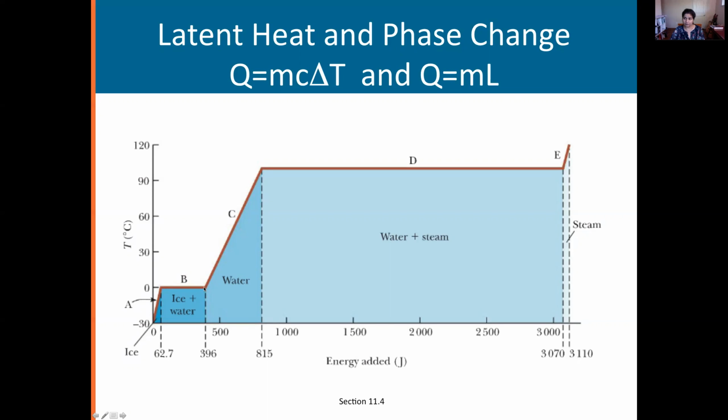Now you have all water in the system. You don't have any ice at this point. And you're beginning to continue to warm the water now. So water is going to increase in temperature, right? You're going to apply Q equals mc delta T now to the water system. So it's going to start warming up, and it'll keep warming up till water starts becoming vapor, right? So water vapor gets formed at 100 degrees Celsius. So at 100 degrees Celsius, we have our next phase change, okay? We change from the phase of liquid water to steam.